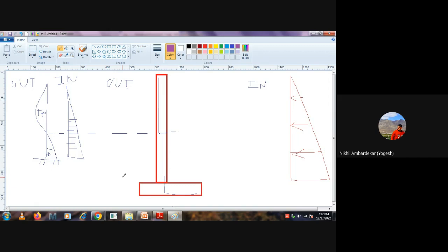Okay. So ideally is this okay? Practically is it possible? Ideally yes, based on the technicality, yes. So your wall is sufficient to take this hogging moment here. But we cannot do it like this. How will we place the bar here? Okay. So this is only the half part.